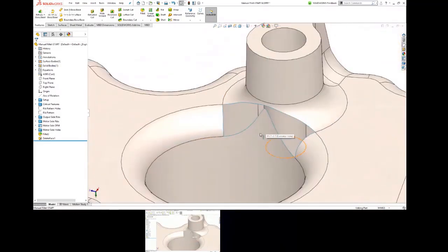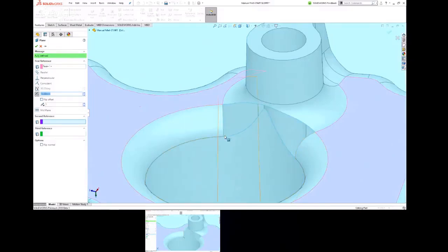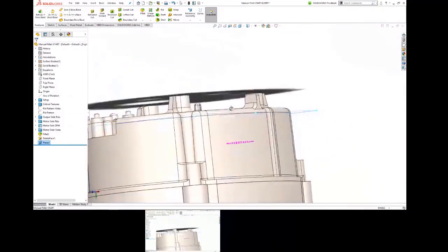So for our next little piece of this solution, we just want to slice away that little bell curve. Easiest way to do it that I can think of is to just slice a little reference plane through there. So let's create a plane. I like to use the S key to get some of those commonly used commands. So a plane that's parallel to this top face here, passing through this point, is exactly what I want.